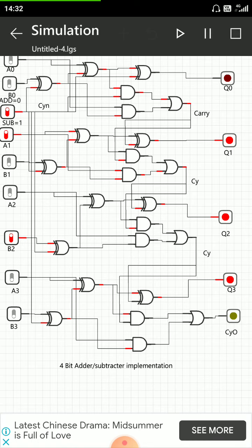By this we can achieve our desired operation. And you can see at the B input I have taken an additional XOR gate, which I have already described. This is a controlled inverter and buffer operation.